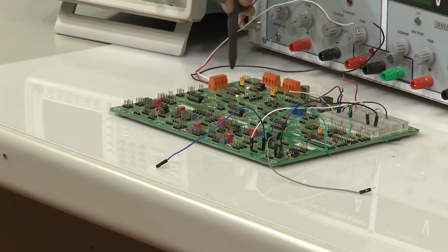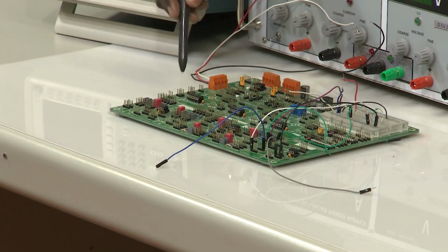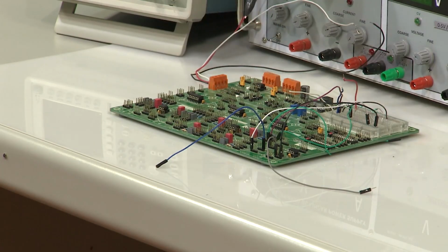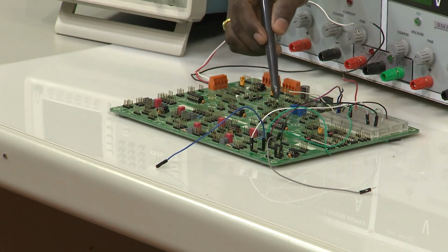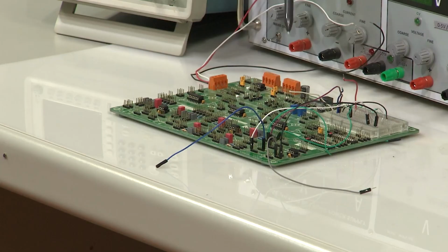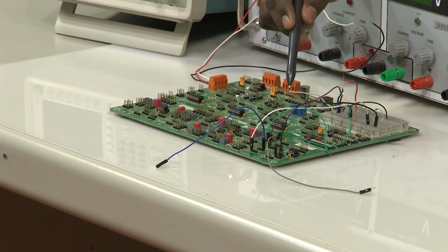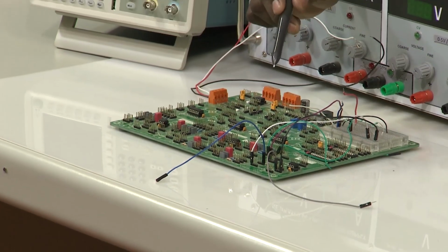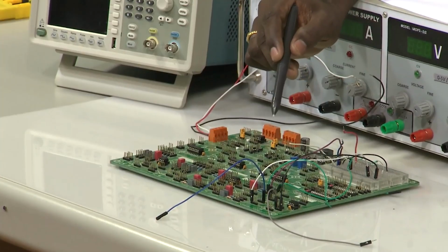Along with these subsystems, it also has an inverting type, a non-inverting type, and a basic op-amp type subsystem too. Right now, in this module, we are going to use op-amp type 3, the basic one. In this subsystem they are using the TL082. As the name itself shows, the TL082 is a TI-based operational amplifier. It contains 2 op amps inside, which means it is a dual channel op amp.